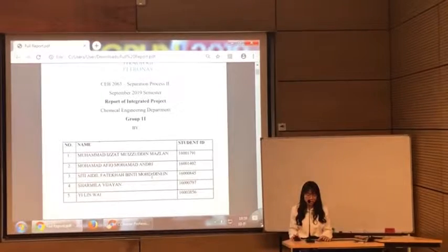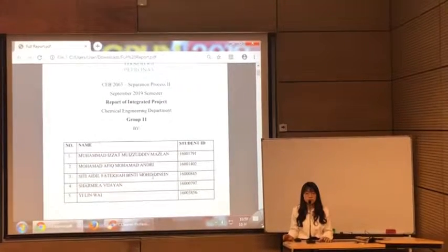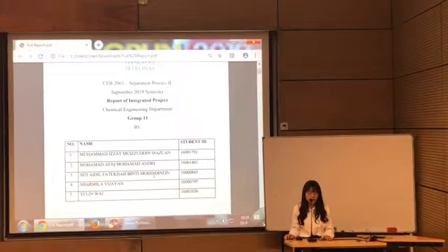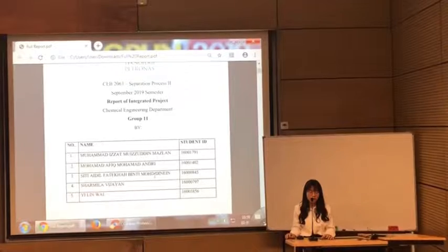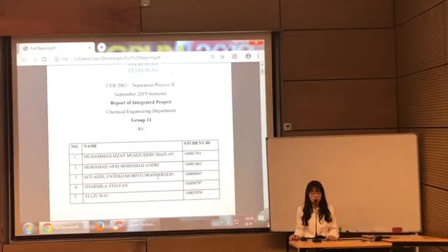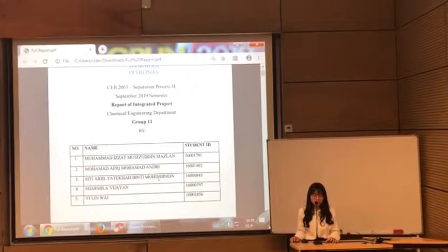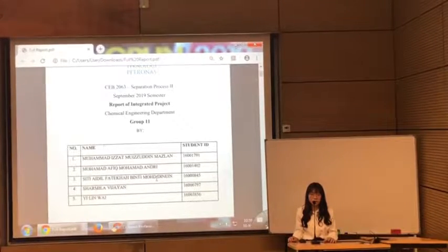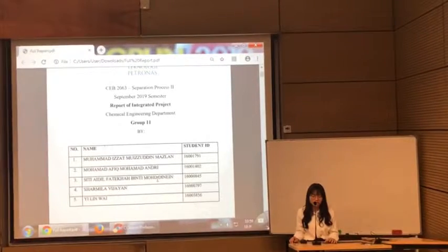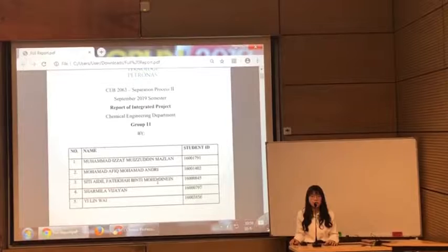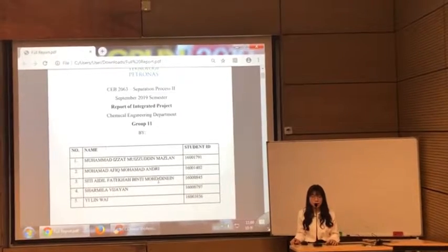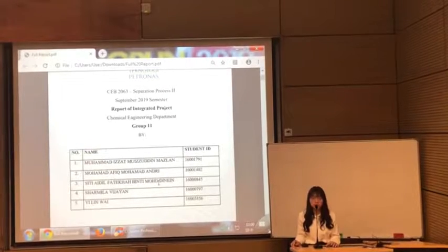We propose this reactor because TBR is suitable for a multi-phase reaction, and it has low energy dissipation rate and high catalyst loading per unit volume, which is commercial for industrial use. The catalyst proposed is multi-wall carbon nanotubes along with palladium tin, prepared using the SI method, the successive impregnation method. This catalyst has a Sn to Pd molar ratio of 0.1.